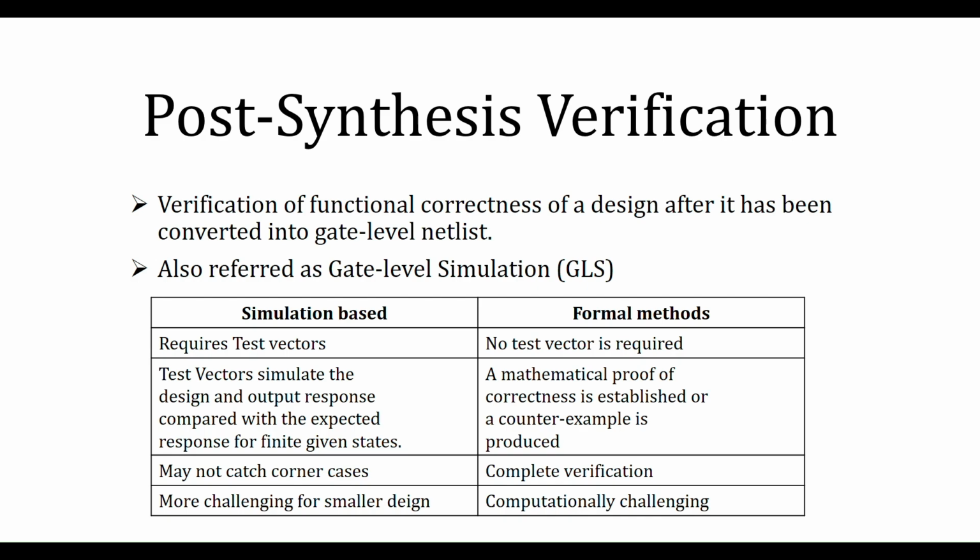The post-synthesis verification can be done using two methods. One is simulation based and the other is the formal method. Simulation based is nothing but a test bench. We will be writing a test bench, so it requires test vectors. A test vector simulates the design and the output response is compared to the expected response for the finite given states. So we may not catch the corner cases. It is more challenging.